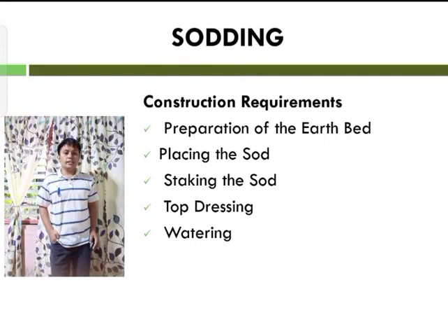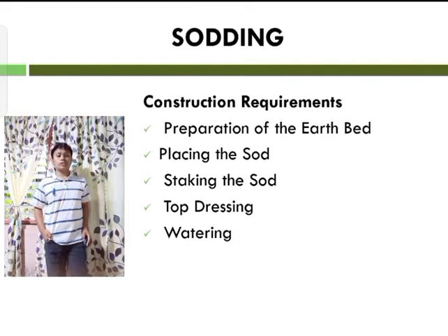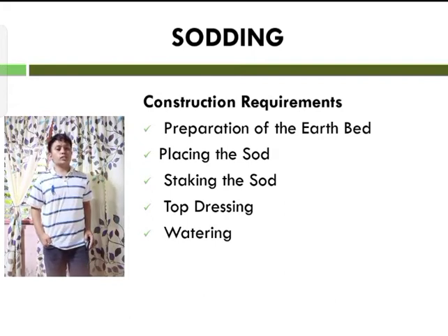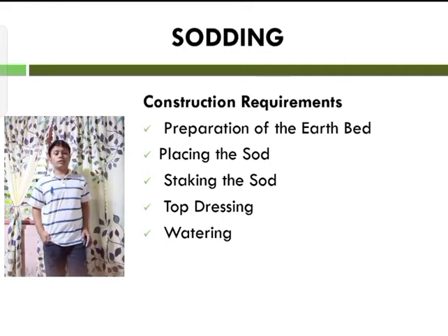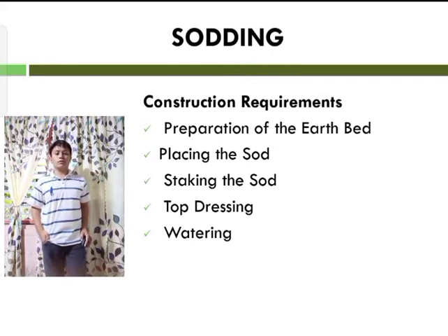So the next one is placing the sod. The earth bed upon which the sod is to be placed shall be moistened to the loosened depth, if not naturally sufficient moist, and the sod shall be placed thereon within 24 hours after the same has been cut. Unless otherwise required, the sod on slopes shall be laid on horizontal strips beginning at the bottom of the slope and working upwards. When placing the sod in ditches and in the construction of sod ditch checks or similar appurtenances, the length of the strips shall be laid at right angles to the direction of the flow of the